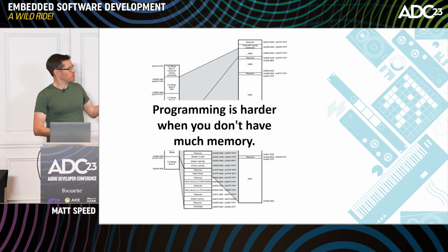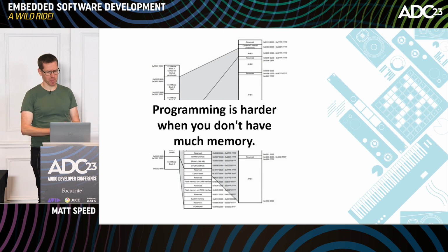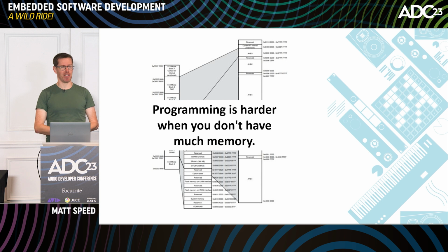And it's not necessarily contiguous. So it may be that there'll be one bit of memory over here you can use, and another bit of memory you can use over there, but it's not in a continuous address space, so you can't just have one big, huge buffer. As a firmware engineer, you spend a lot of time staring at the linker map, wondering why you chose this profession.